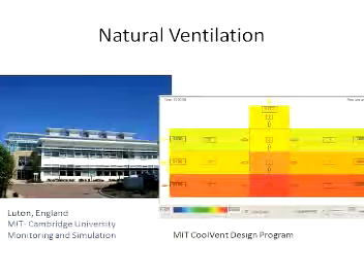It turns out if we have operable windows or other openings to the outside and carefully design the interior volumes so the air can freely flow through the building, we can find that for some or all of the time during the summer, we don't need to use the air conditioning. We can, in fact, allow the airflow from the outside to provide comfort conditions in the building. And numerous studies have shown that people in naturally ventilated buildings are much more comfortable and are more productive than people in the sealed up buildings that we normally think about.